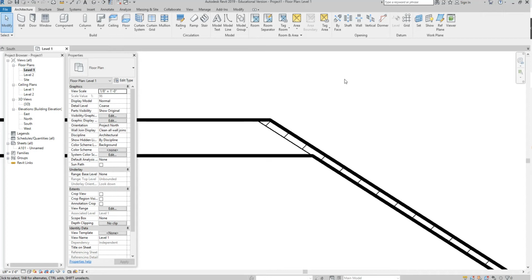In AutoCAD, we have to very manually go in and create layers and assign those layers colors, and then we have to use a pen file to print in order to make those thicknesses show up on our drawings. In Revit, these are inherently defined for objects. And I think generally they're pretty good, so I tend to not change those either, right? I think Revit is not highly customized out of the box, whether you purchase it or use it as a student, but it is defined well enough that you can go in there and just start working, which is one of my favorite things, right?